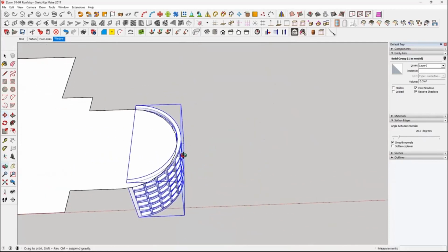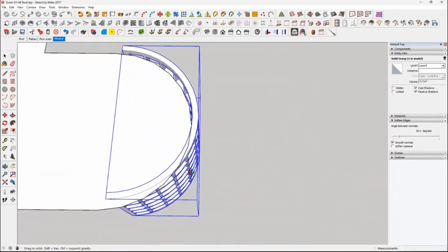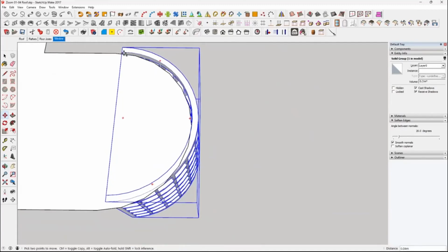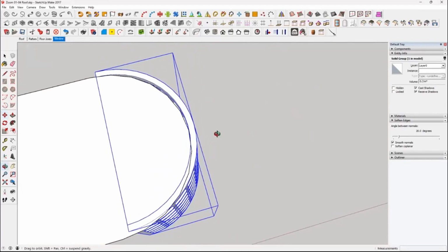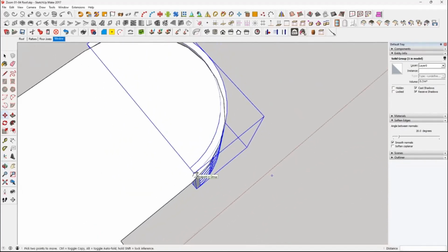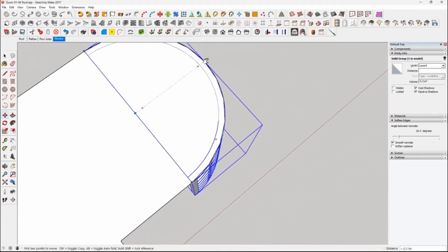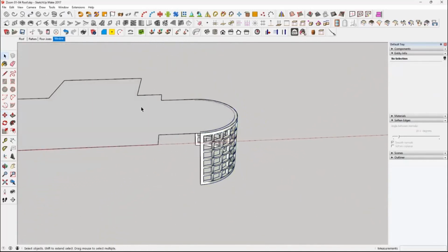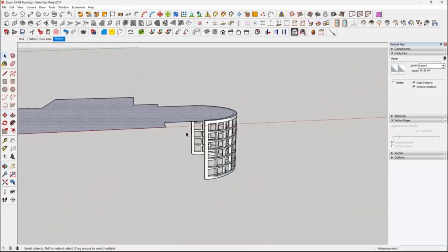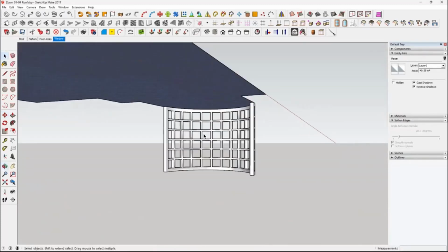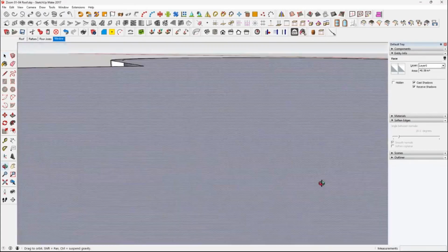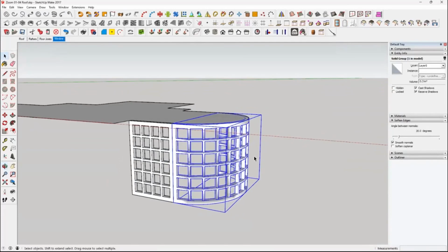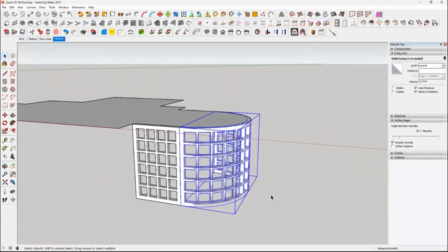And we couldn't have got the right one because it's moved. It's not moved in the right place. Easily sorted. Click on an edge, go on the green axis. Nowhere near, was I? There we go. So that could be your roof. And then we can go inside, and then you've got a perfectly good bay window. And this will print in resin printing, lovely.